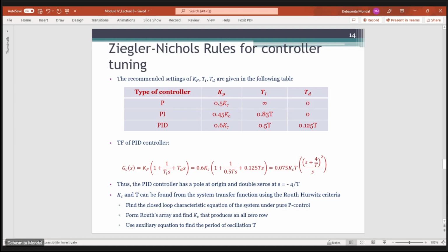And obviously you have the other parameter also. You can always change the value of the feedback depending on the specifications of the system that is provided. Now if you take this PID controller with these three parameters into consideration and write the transfer function, you can simply substitute the values of Kp, Ti and Td. This is the transfer function of the PID controller, given by this expression.